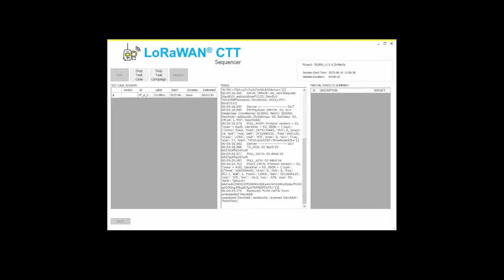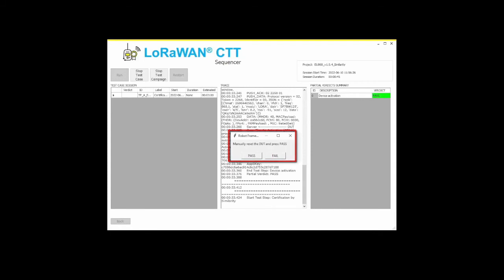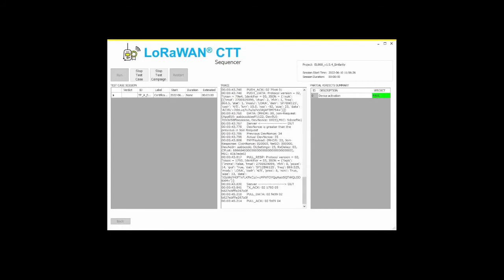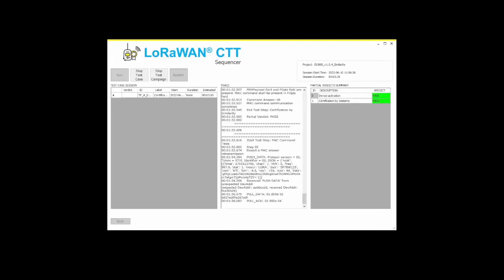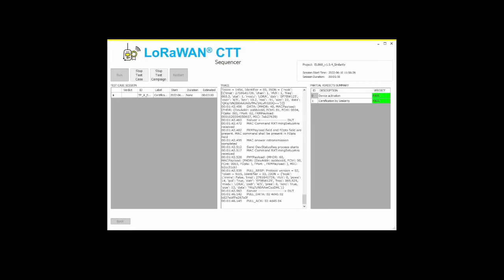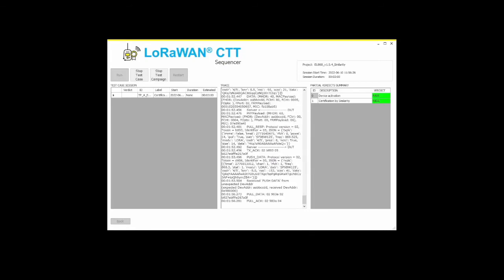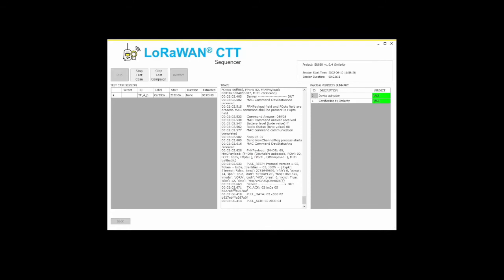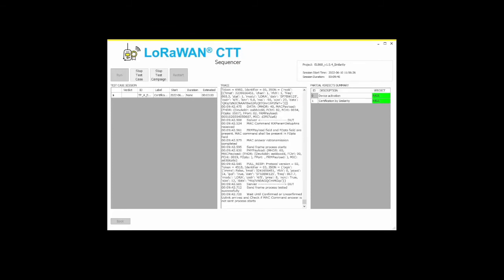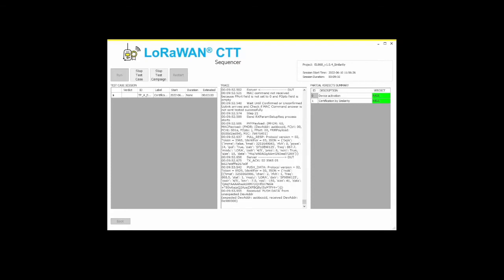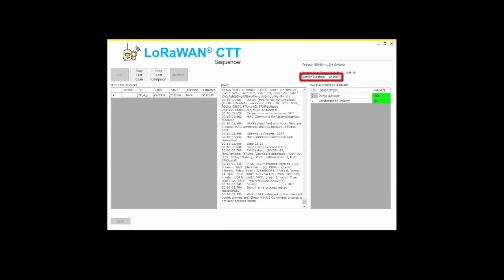After a successful activation, you should follow the instructions of the LCTT and reset your end device when required. For this testing, the certification protocol running on port 224 is not needed and the whole testing is run using the standard application. The only requirement is that the end device is configured to send uplinks periodically, and it's recommended that the device is set with a faster periodicity for a quick execution of the test. For example, this could take less than 10 minutes if the uplinks are sent every 10 seconds.